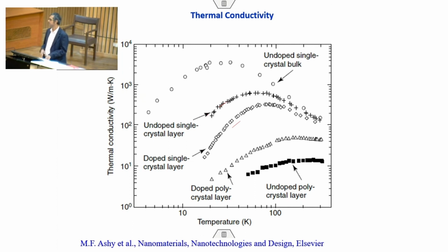Okay. So hence, as you can see here, for 2D nanomaterials, the effect of dimension is very distinct and clear on the thermal conductivity. And this can be easily explained by considering three important aspects. First, the confinement effect because of electrons or phonons. Second, the scattering effect. Single layer scattering is less, multi-layer scattering is more. Okay, in a multi-layer, between each two layers you have an interface that will act as a scatterer. Secondly, even if you have polycrystalline grains in each layer, the grain boundaries will act as scatterers. So that will further reduce the thermal conductivity.